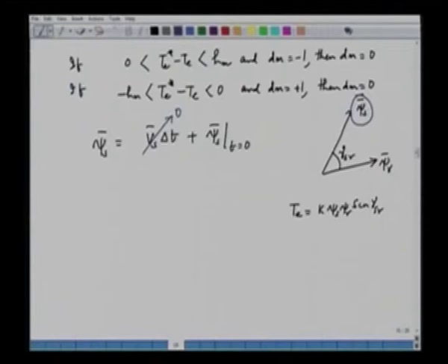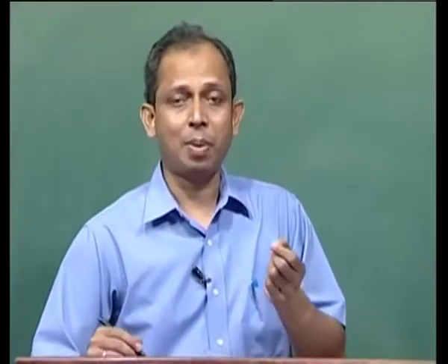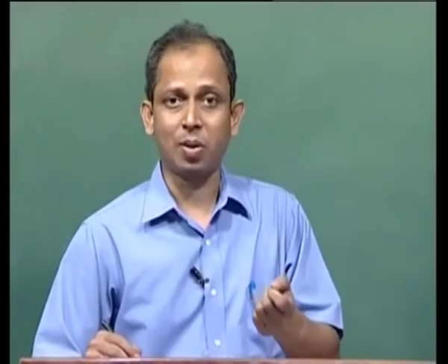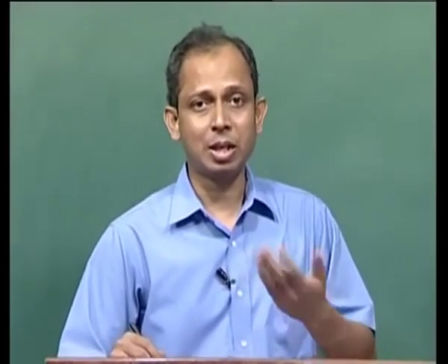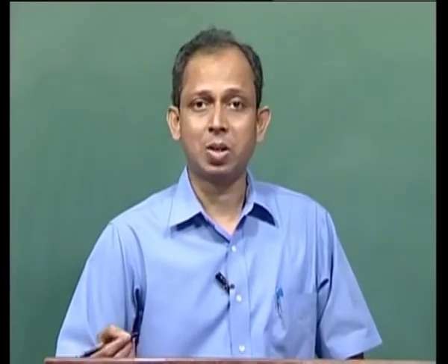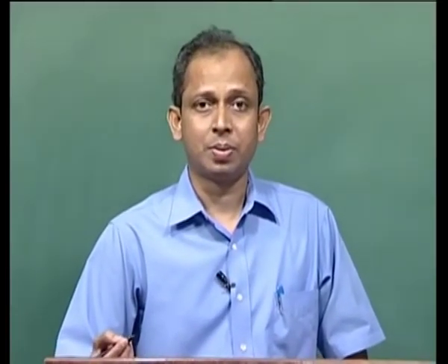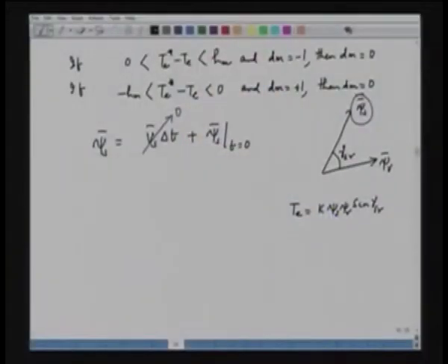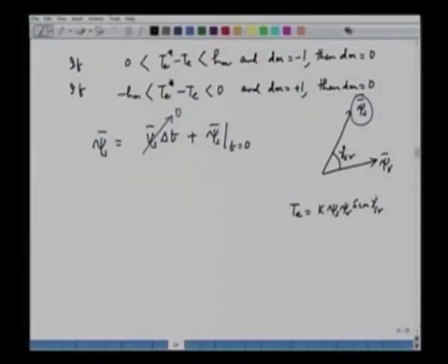So suppose you apply Vs equal to 0. If Vs is equal to 0, the flux is neither increased nor decreased. We know that psi s equals psi s at t equal to 0, because we have applied a 0 voltage vector. So by applying a 0 voltage vector, we are freezing the flux. It means the torque is neither increased nor decreased. So that is how we can maintain the status quo of the torque unchanged. So this is about the various status of the flux and the torque.